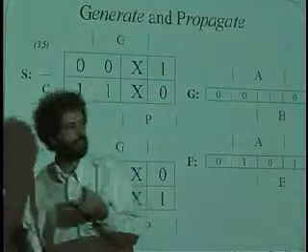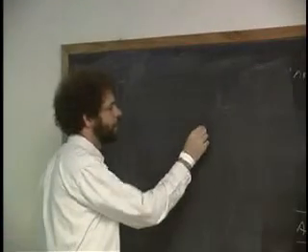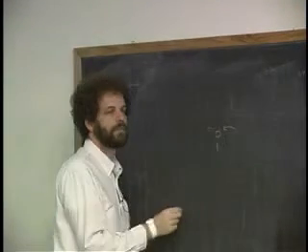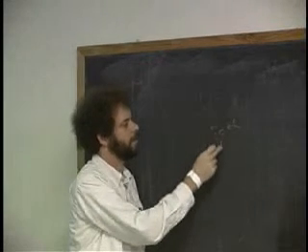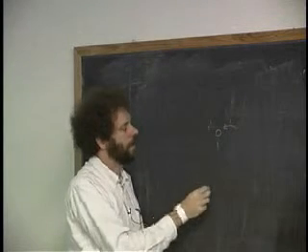There's really two cases that we need to think about here. One is if I'm adding together numbers and I have one particular bit, if the carry were to come by, would I want to continue to propagate it further on in the chain? Well, when's that going to be true? I'm going to want to propagate the carry when? If it's 0 and 1 and a carry comes in, should I propagate the carry out? Yes. 1 comes in and a 0 and 1, should I propagate? 1 plus 1 is 0. Yeah, okay, so that's one case.